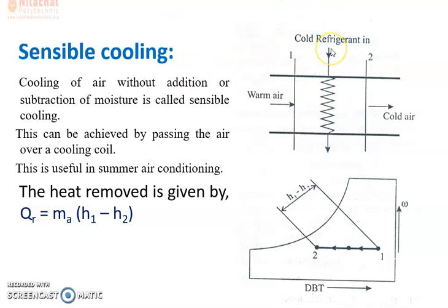Instead of heating, here you are cooling. In sensible cooling, the cooling coil may have refrigerant, cooling water, or cool gas flowing through it. Sensible cooling can be done only up to the dew point temperature. Mind it, sensible cooling is done only up to the dew point temperature.